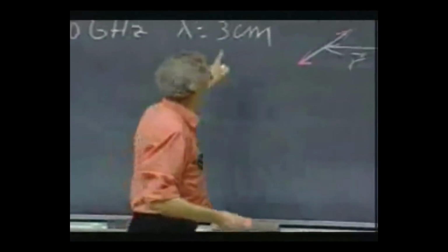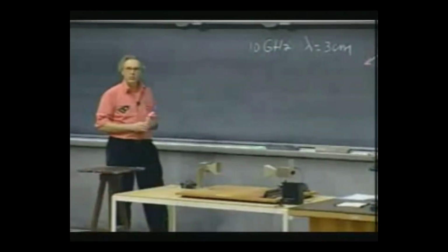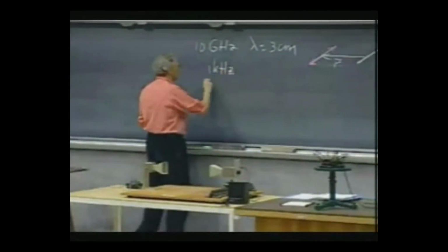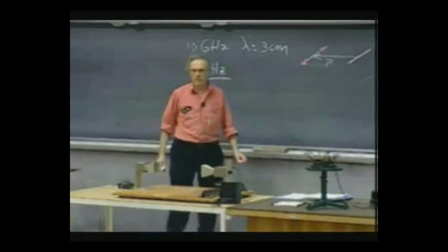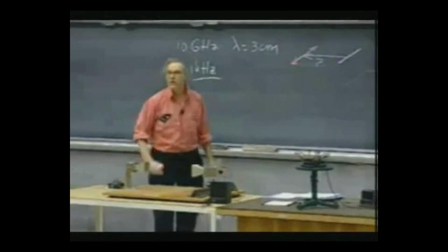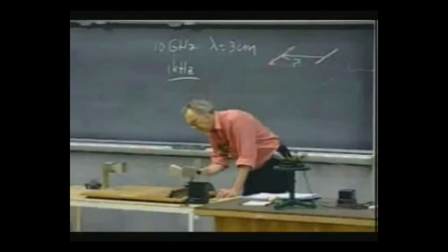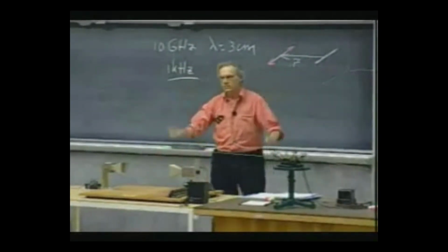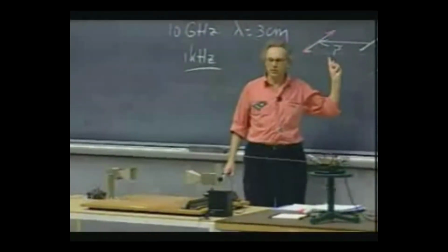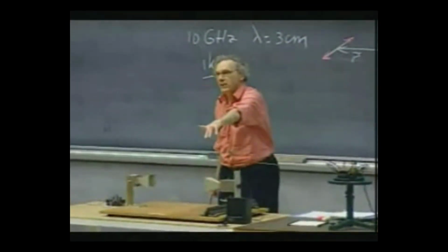We have modulated this signal with an audio signal, amplitude modulation, as we discussed earlier, that you also use with radios. And we modulated with approximately a 1 kilohertz audio signal. And we'll make you listen to that audio signal. And you can tell then that this receiver is indeed receiving the 3 centimeter radar from this transmitter. That's what we will first do. So I'll just turn on the transmitter, and here you hear 1 kilohertz. This is the modulated signal, and it's received by this antenna, which is a straight wire like this,